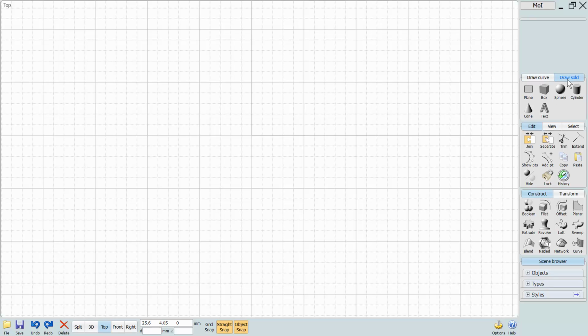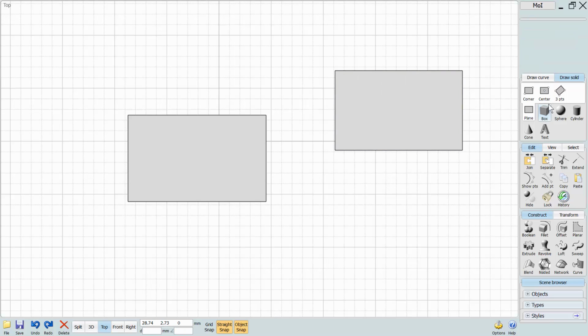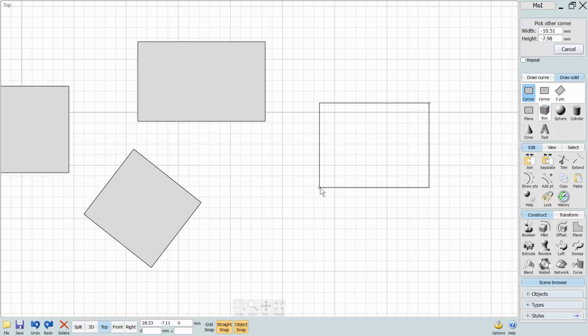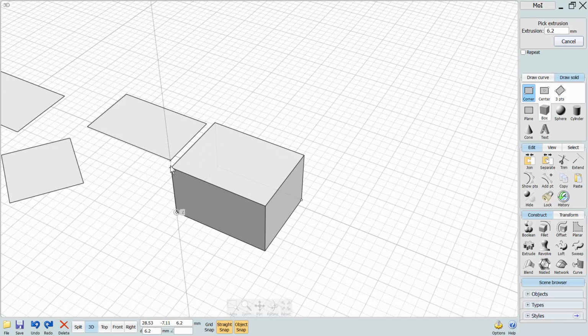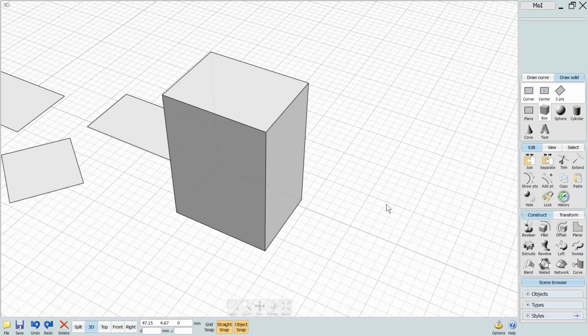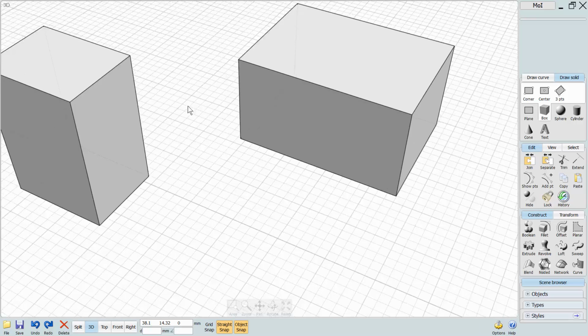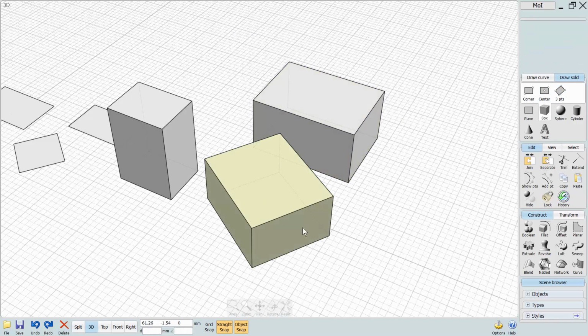Let's move to Draw Solid panel. In this panel we have 3D primitive creation tools. You can create a plane like this. You have 3 methods, with center point, with 3 points also. You have box tool like this. You can create a base and then extrude up. Moi will snap your mouse to this point, so you can extrude like this, or you can create this base with center point and then extrude up like this. And also we have 3 points, so that's super basic stuff.